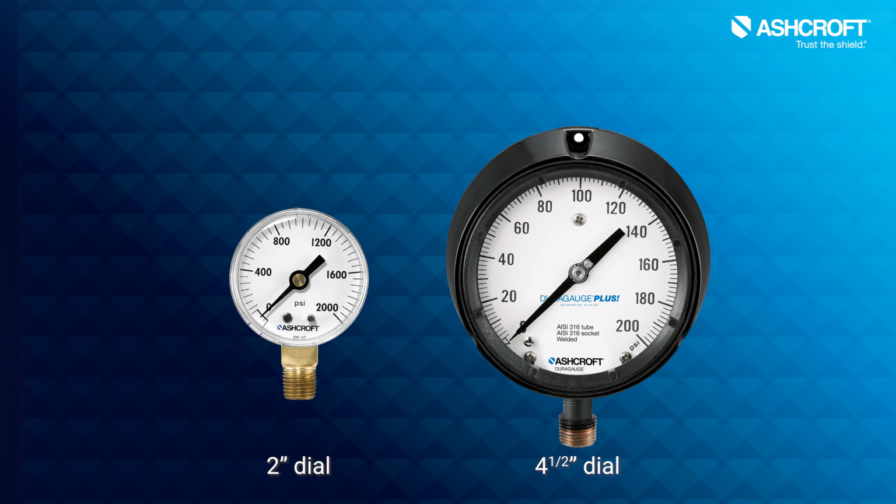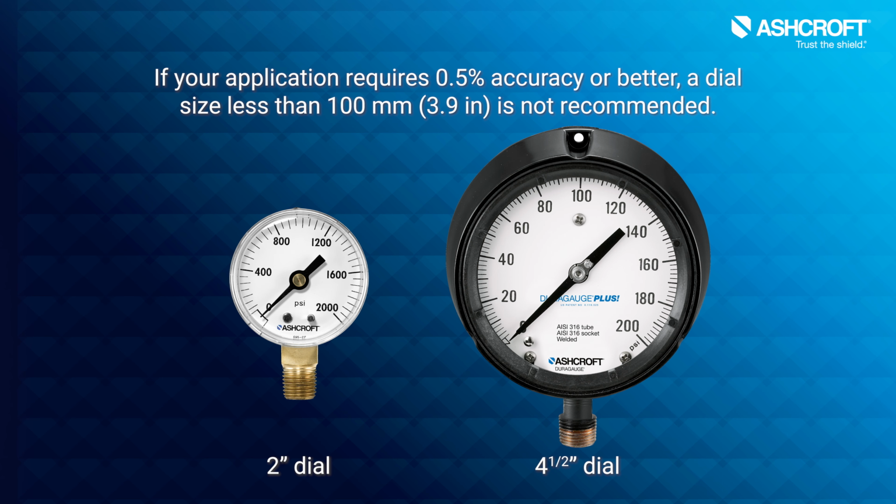So if your application requires 0.5% accuracy or better, a dial size less than 100 millimeters is not recommended. That's because the number of required graduations can make the gauge difficult to read. In these cases, consider getting a dial that's a larger size to accommodate the measurement increments.